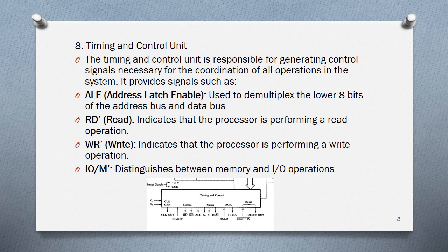So what is ALE? ALE is used to demultiplex the multiplexed address and data lines. So these address lines will carry the data now. So that is the need for the address latch enable signal.